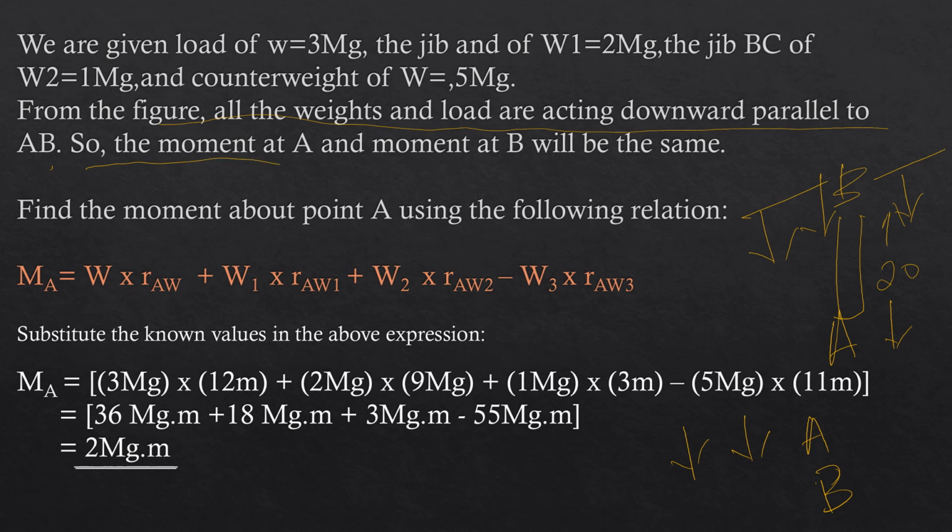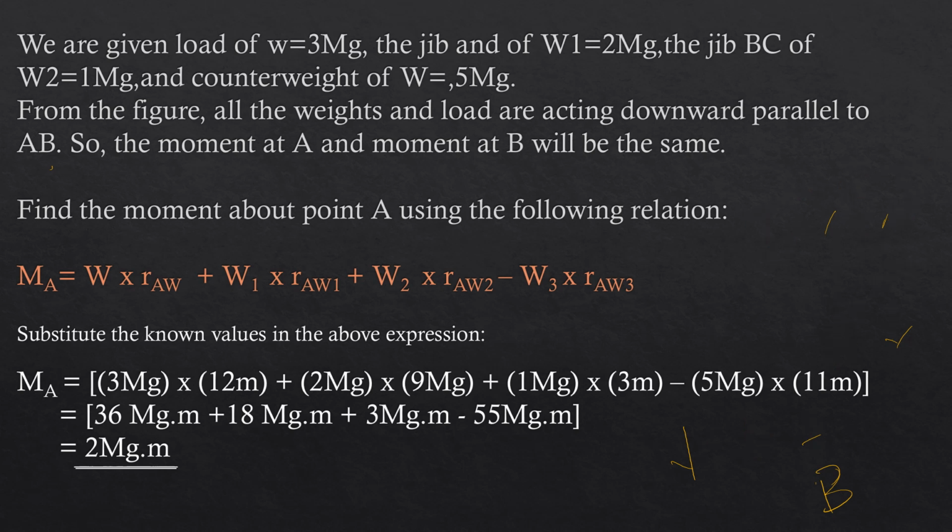So the moment at A and moment at B will be the same. You might think how it's possible. What did I say moment is? Moment is basically force into the perpendicular distance. Here the force is given, and the perpendicular distance for point A and point B is the same since it is parallel.